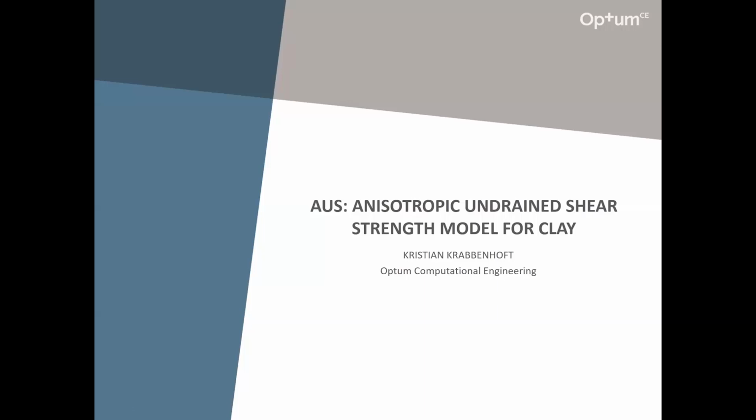And as you mentioned, this webinar in a way follows on from our webinar last week on sand, where we discussed the fact that the friction angle is not constant. It depends on the stress level. I mean, it depends on the density and the kind of material you're dealing with, of course. And then it depends also on the stress level and on the stress state, in the sense that the friction angle in plane strain and triaxial compression usually are different.